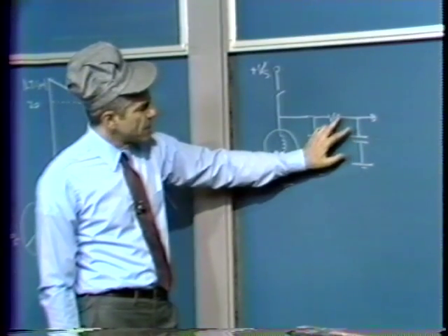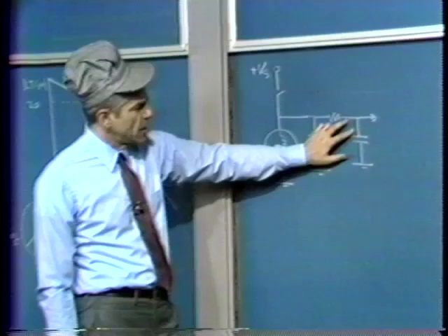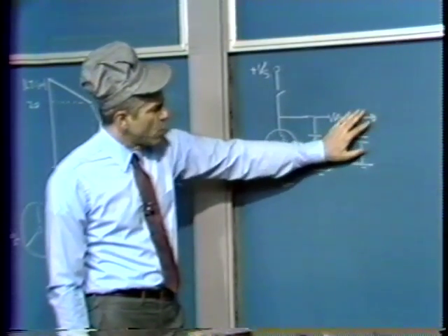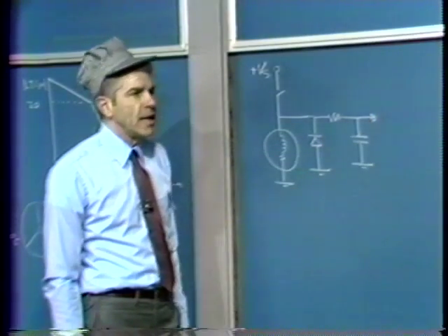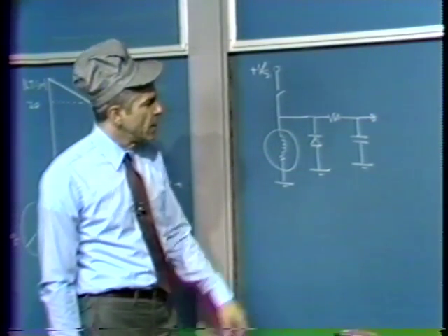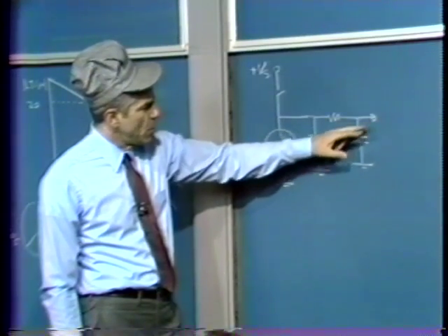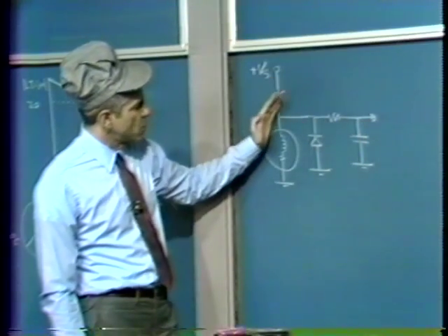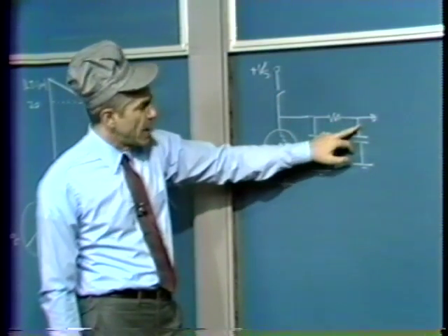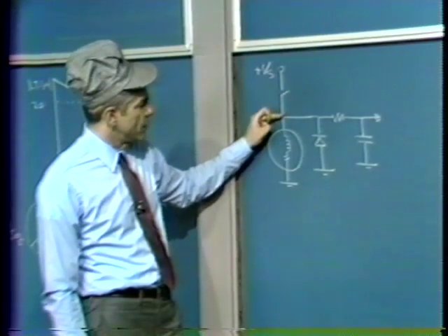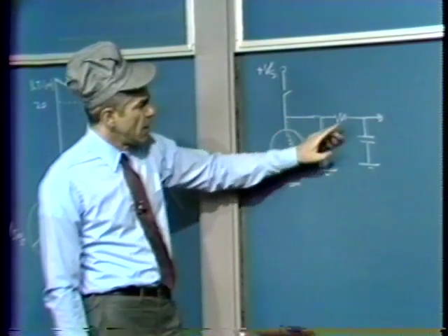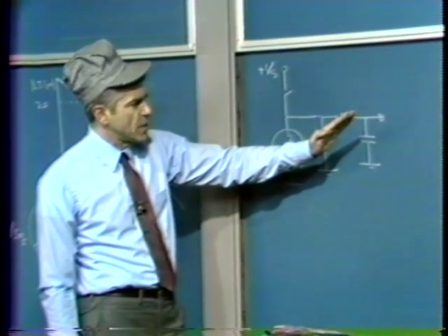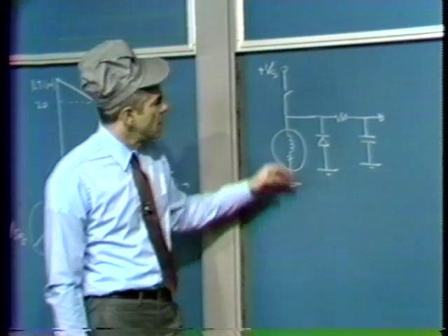I won't go into this in detail, but I do discuss it in the book, I believe in chapter 11. You can use a Schmitt trigger, and what happens then, you apply your command to one side of the Schmitt trigger. When the command voltage exceeds this RC voltage, you close the switch, and the voltage on the capacitor begins to increase. When you have the switch closed, you've got the full supply voltage at this point. The capacitor voltage begins to ramp up a little bit. Pretty soon it exceeds the hysteresis on the Schmitt trigger. The system switches. The switch opens up.